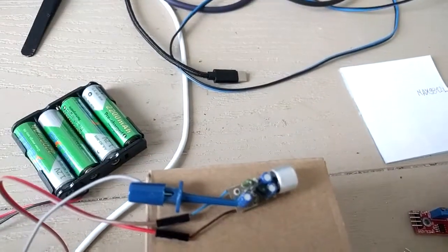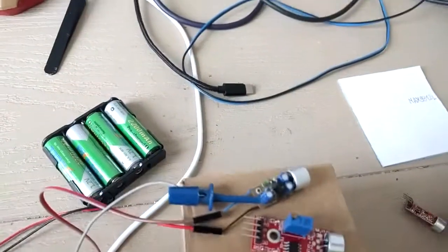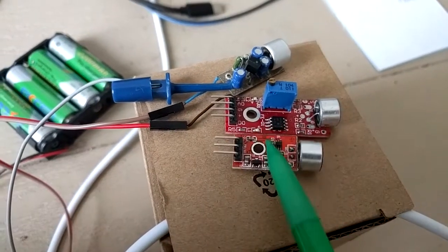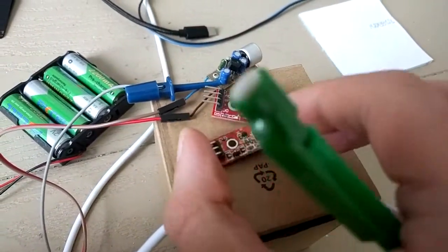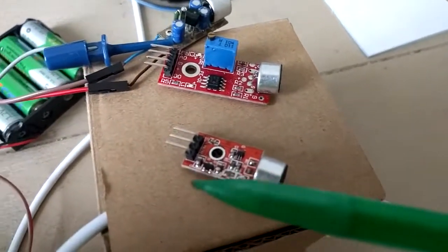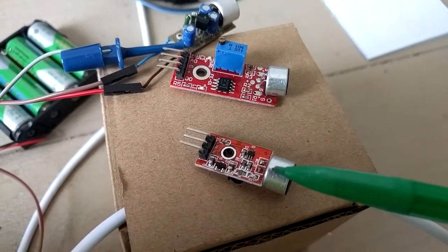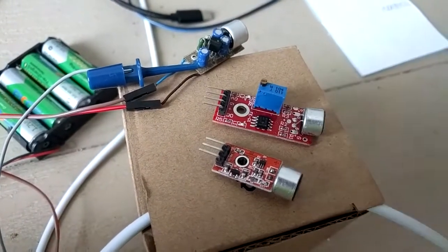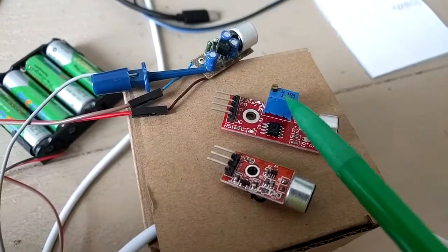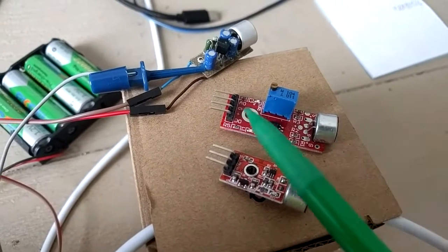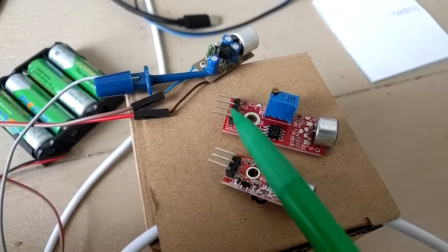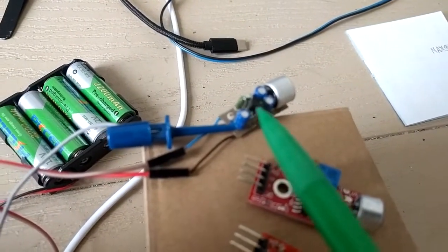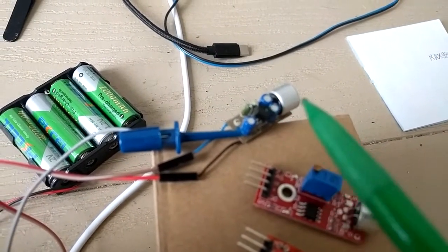To conclude, among those three microphones, only that one is acceptable for our use. It has a good output signal and acceptable distortion level, around 0.2, 0.4%. That one has similar distortion, but the output signal is very low, not good for the measurements. This device has huge distortion, so it's not acceptable for the measurements.